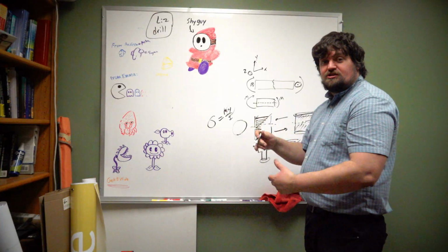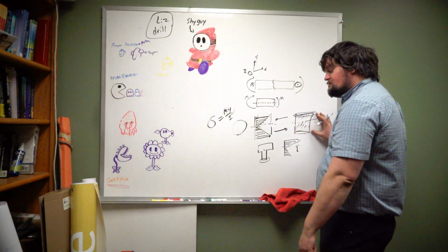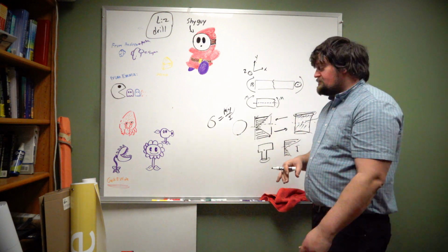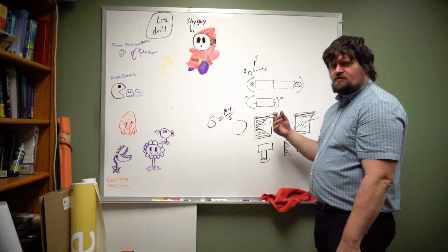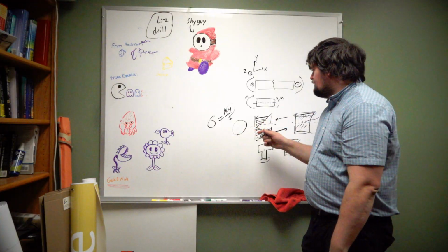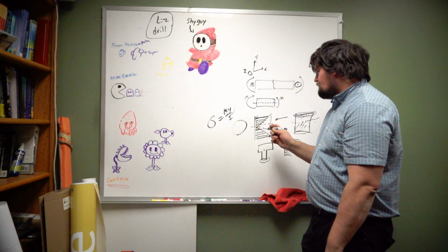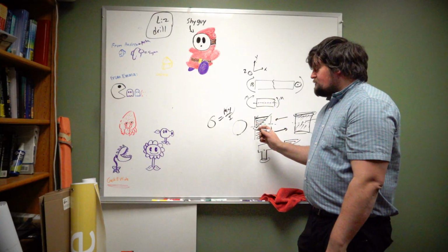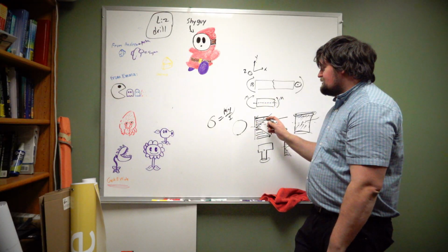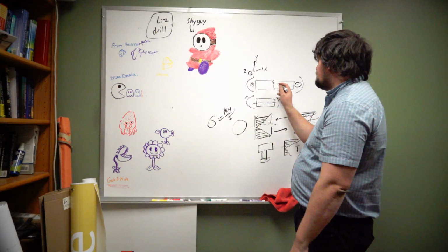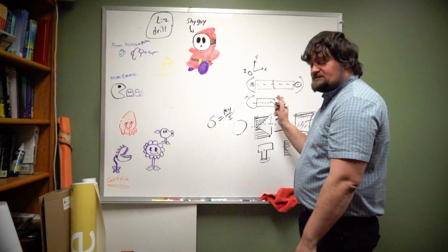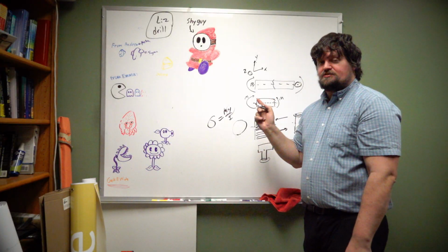So we have net shear loads acting between the top and bottom interfaces of this, and that creates our moment across our cross-section. Now, even though these are shear loads, these shear loads are acting in the x direction. And you'll notice that's also the axis of our system.